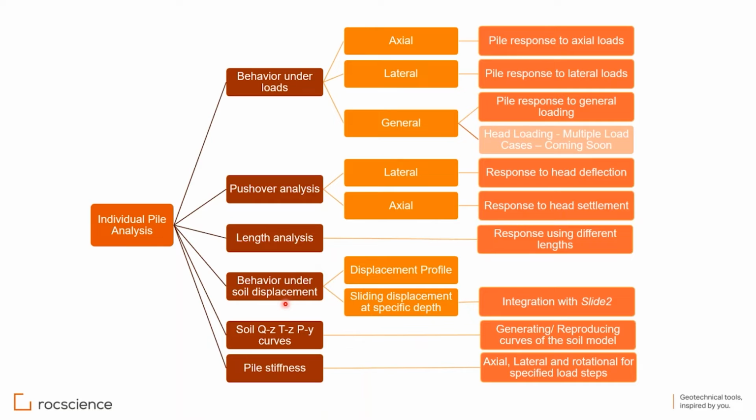We also have behavior under soil displacement. So you can have the soil moving, and the movement of the soil will affect the pile. You can have a displacement profile applied to the pile, or a sliding displacement, like a block of soil above a certain depth that starts moving along the slope inclination. And this is integrated with Slide2 perfectly.